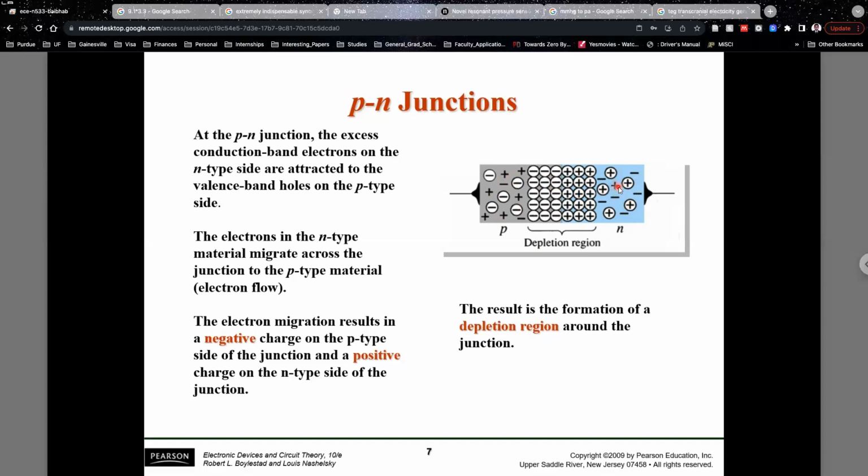That's because of the inherent properties of the devices: if you have energies in the electrons and holes in the inherent structure, they can break the atomic bonds and they can move around the entire structure. But the number of those electrons and holes will be very small. So that's why you can still have holes in the N-type material, and you can still have electrons in the P-type material, but those will be called minority carriers. The number of them will be very, very small, usually in the range of, like, if there are 1,000 holes in the P-type structure, there would probably be one traveling electron in the P-type structure.